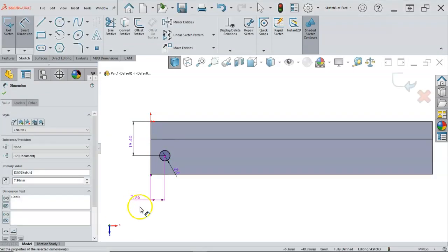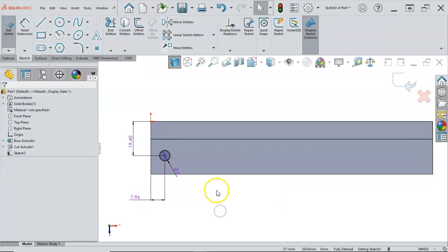All right, so because we have that dimension, our 140 would give us 10 on each end if this was symmetrical. So I'm always looking for that symmetry, and if there is a reason that this is offset, then we can kind of identify that and be aware of it.